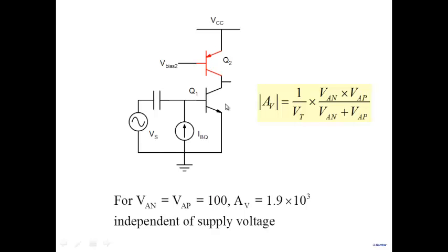All right, so we'll see that as a problem later on. What you would find is one or the other transistor in general will leave the active mode. One will win, the other will lose, and one of them will go into saturation region. Let's say Q2 may remain in active mode and Q1 may go into saturation. So Q2 wins and remains in active mode, drives the current here, and Q1 accepts whatever Q2 drives. But then we lose. We want both the transistors in active mode. Then only we get gain.